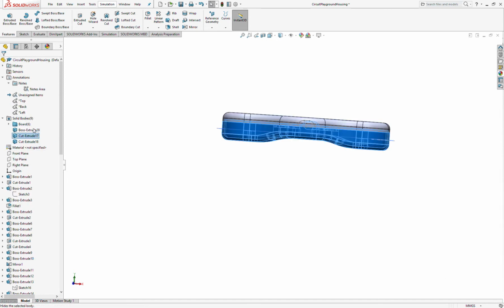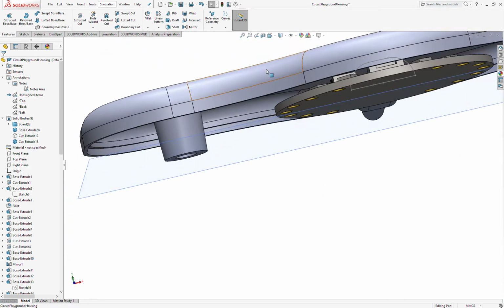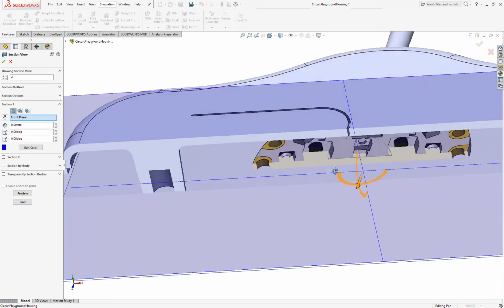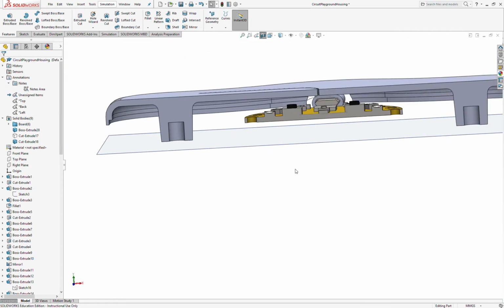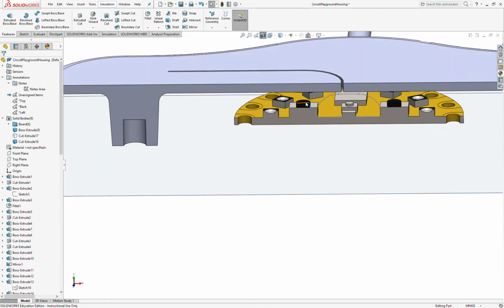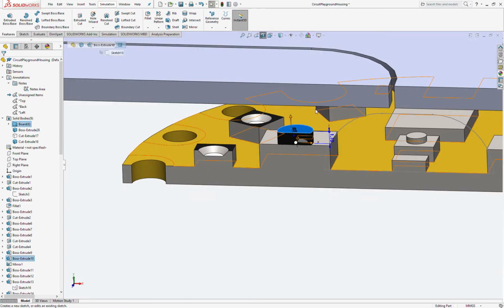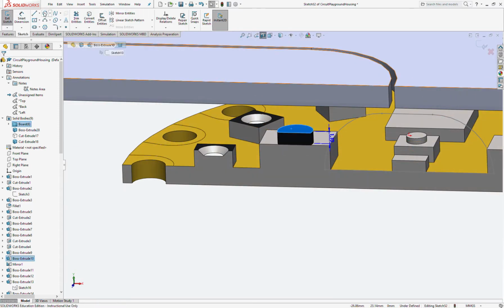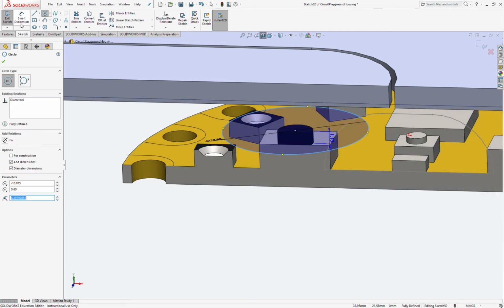So we're going to hide the bottom. So now we just need a contact, basically. Something to actually hit that button. Being that I modeled the buttons in their uncompressed position, I can actually model this thing to basically sit right on top of it. And it'll work really well. So all I need is a pad.